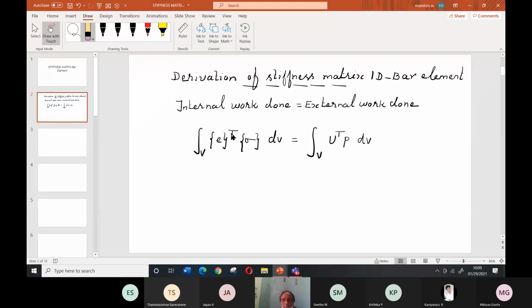So what you have to keep in memory is the story of the finger I told. I am displacing it by the other finger. Can you do it, all of you? Just do it and see how your finger is deflecting. It's like a cantilever beam, and it is getting deflected. Load is applied, it is displaced. So that's load into displacement. That's external work done, which you are able to see.